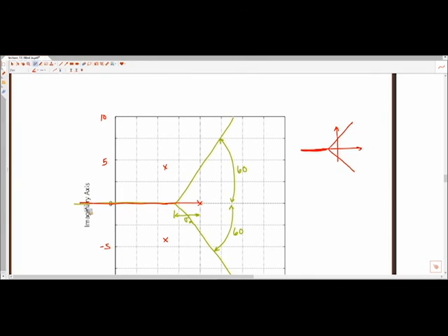And so in terms of this root locus plot, we have figured out what one of the branches does. We'll talk about the other 2 on Monday because I'm out of time. But this says, as I increase this gain k, the closed loop pole associated with the pole at the origin is going to move to the left, and it's going to keep on moving to the left, all the way to negative infinity if I keep on cranking up the gain. It says nothing about the other branches yet, but it says something about this branch.